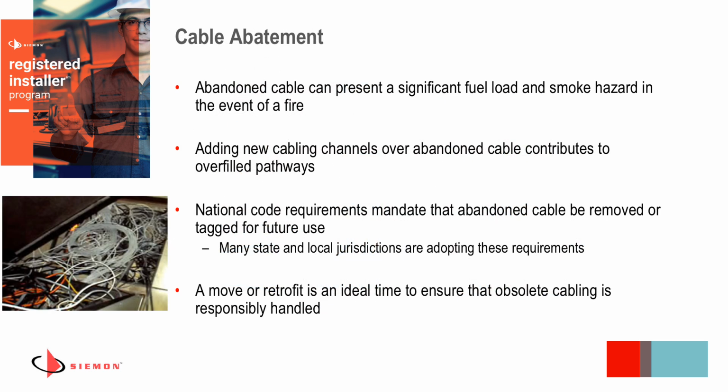Now this slide is an informational slide as it relates to cable abatement. Structured cabling should minimize a lot of that, but historically a lot of customers have installed cabling from point A to point B over the years, and the solution to having a new connection is just to run a new cable and not remove any of the existing installed cables. The trouble is, if you look in some of these pathways, they have a significant number of abandoned cables, and it's quite a heat load if there is a fire, not only heat load for fire burning, but also smoke hazards. So, adding new cables over there is not the solution for that.